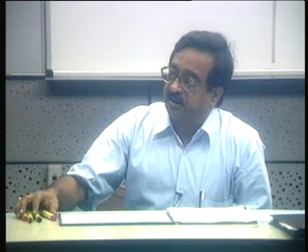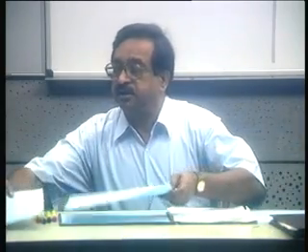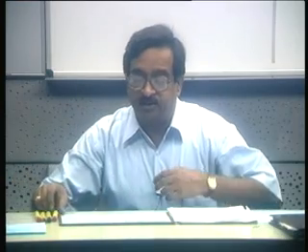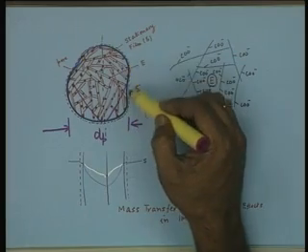So, therefore, the two major matrices which provide resistance to the overall reaction are the thin film around the immobilized enzyme particle and the whole matrix itself, and the pores in which the immobilized enzyme is distributed. I think you will also recall the diagram we had seen earlier, that you have a thin, stationary film around the particle.